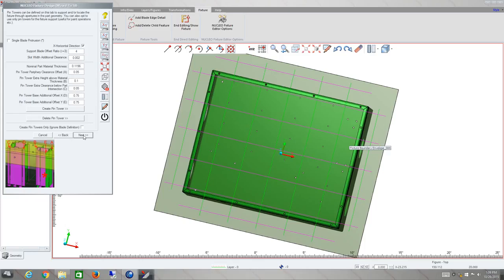This option is a pin tower option, where you would have maybe traditionally put a machine pin in a fixture, so you could locate through a feature in the weldment. This does the same thing. What you do is you choose a circle or a square, whatever shape you like, and you pick the edges of the square, and it will then project a tower underneath that position, so you can locate through that feature in the weldment model.